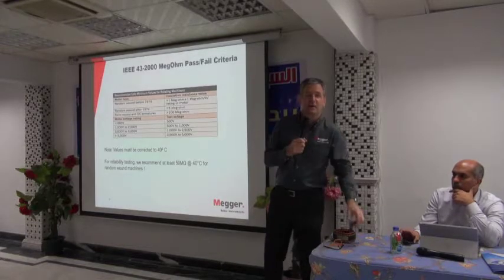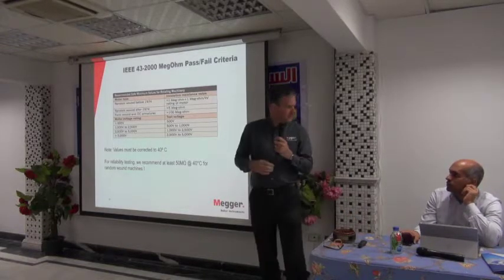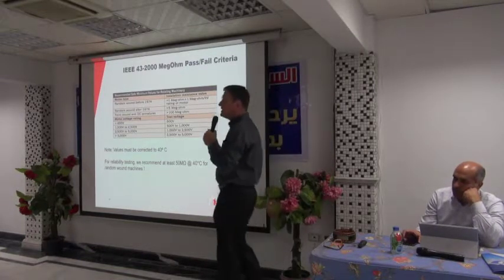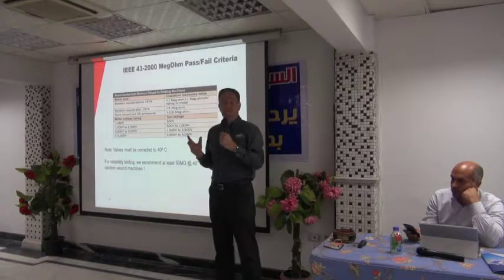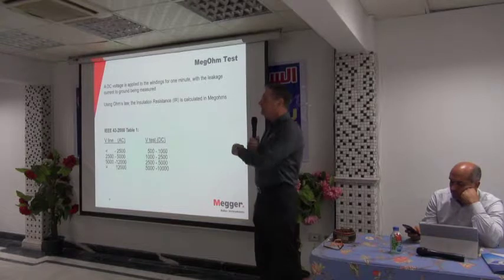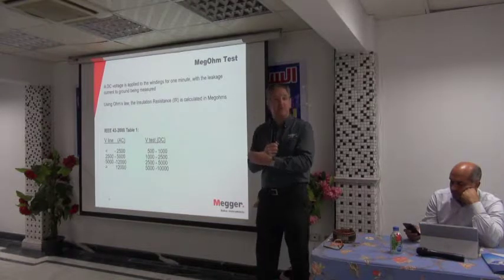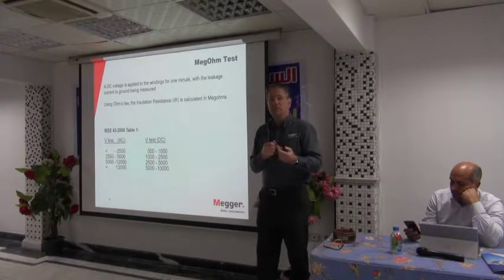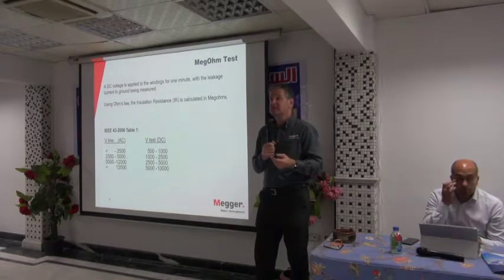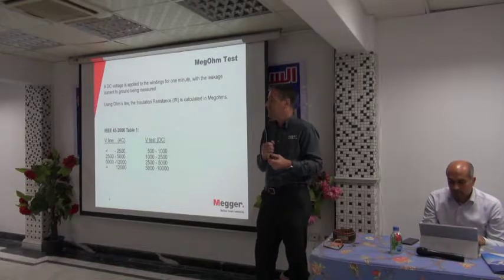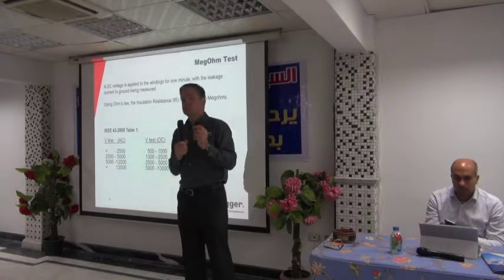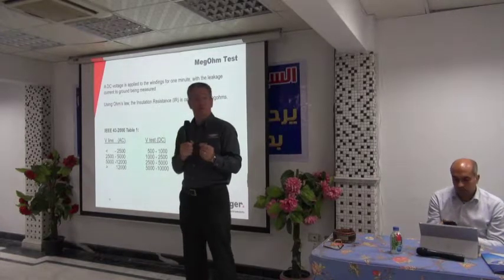There's one other thing we didn't cover, just briefly. One thing we didn't cover about the megohm test, we looked at the standard for voltage. So we discussed that, and we agreed that your company followed the standards for voltage, which is very good. What's the minimum megohm value that you look for when you make a megohm test?